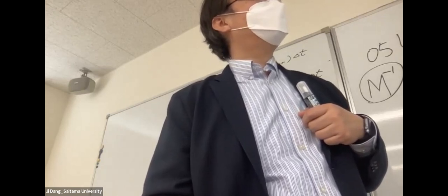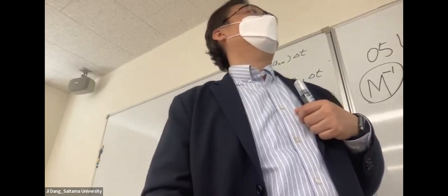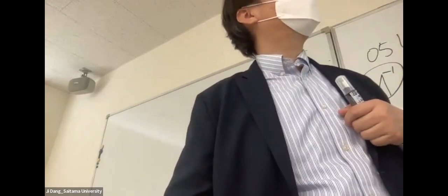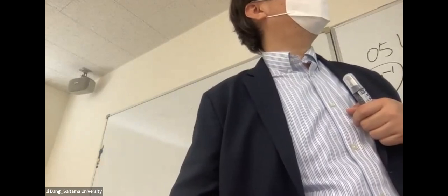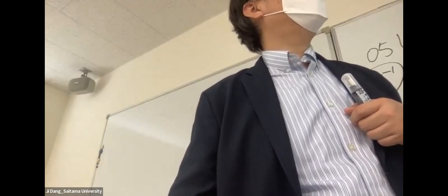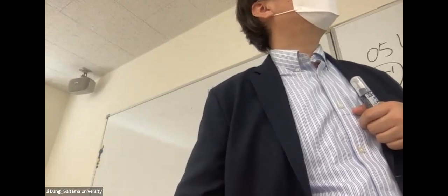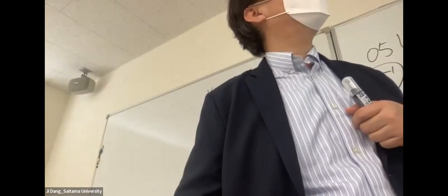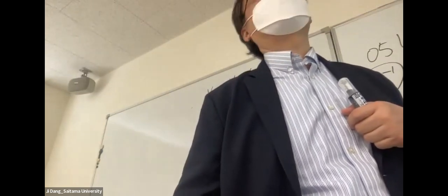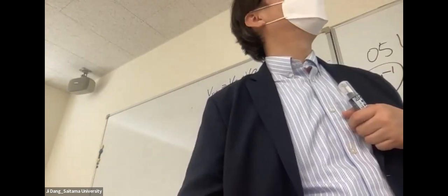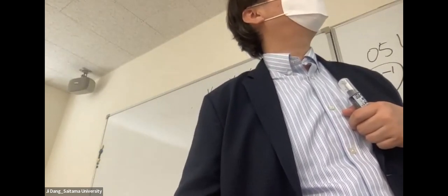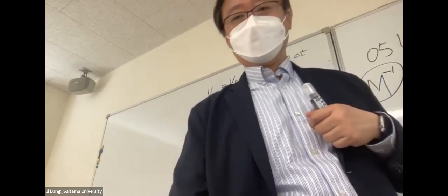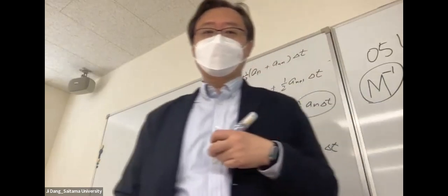So for the acceleration, we just directly correct them by minus this term, okay? This should be minus. And for the velocity, we already predicted one, and then we use this part to correct them. We use 1 divided by half and delta t, because error is generated in the source of delta A. Same for the d, we also use beta delta t square to calculate the correction.